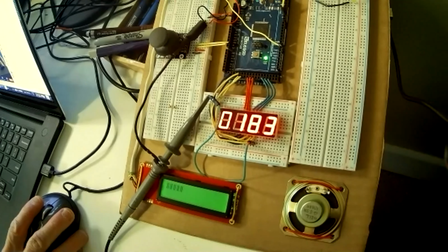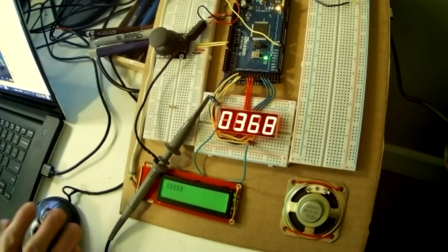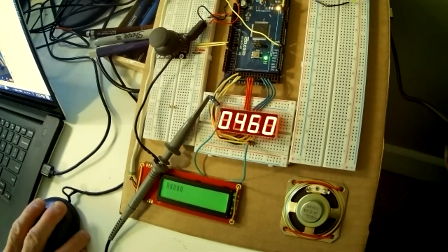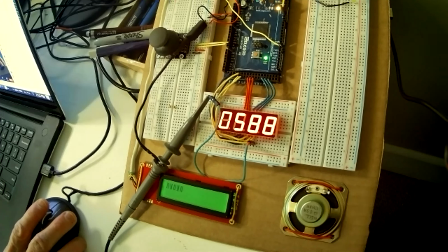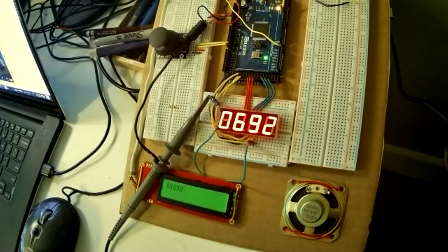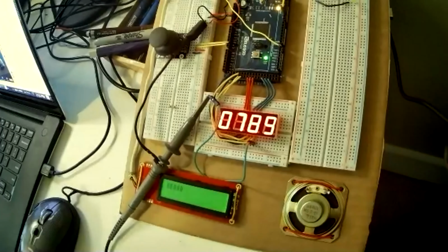I'm sorry, not 200. 50 milliseconds is 20 counts per second. And that's totally done right. So anyway, somewhere in there, this is showing how much we can pump data through that queue send mechanism while it's still working reliably. And this is a kind of testing you should try to do in your projects. Try to push it until it breaks so you have confidence that you're well below that breakage margin.